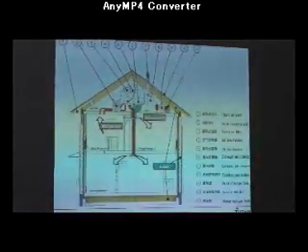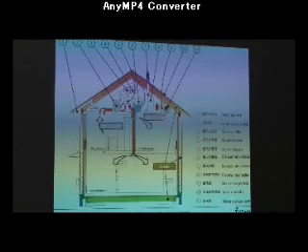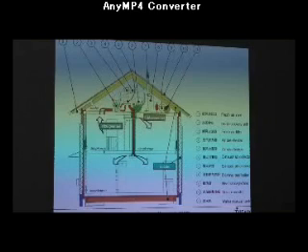This illustration shows the facility system in this housing unit. All the facilities were installed in the attic of the housing unit. The heat in the exhaust air can be recovered in the heat recovery air handling unit and transferred to the fresh air. And the fresh air can be further preheated by solar energy and distributed to every room in this housing unit to keep the room temperature